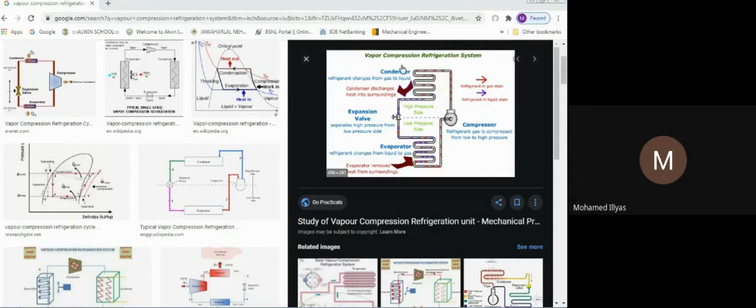It is passing through the condenser. When it comes through the condenser, we use some external arrangement, an external cooling fan or something like that. We convert vapor refrigerant into liquid refrigerant here. We extract heat from that. Phase change is taking place. So vapor refrigerant is converted into liquid refrigerant, theoretically at constant pressure. It is already a high pressure, high temperature vapor refrigerant coming down. We are just cooling it, converting it into liquid refrigerant. The pressure remains the same. There will be a small pressure drop here.